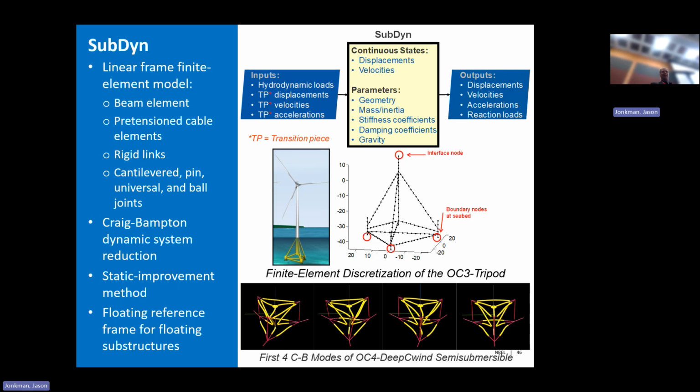Just have the stiffness. Don't worry about inertia. That's really needed if it's a statically determinate structure. It allows you to get all that flexibility in there without tracking all the dynamics of all those modes. It's a pretty powerful feature. It allows you to do, again, big models with lots of modes, but limited computational expense.